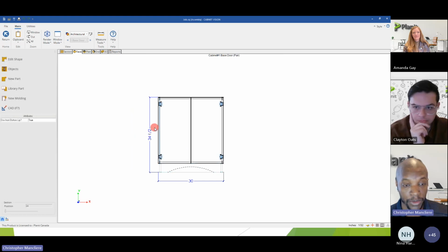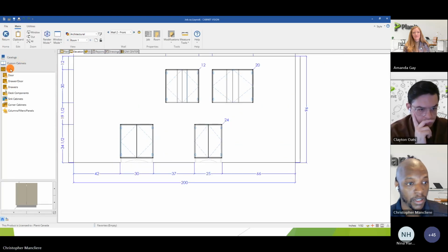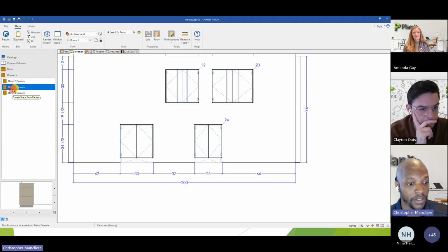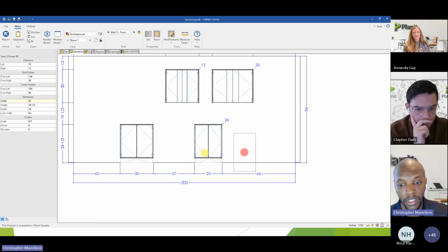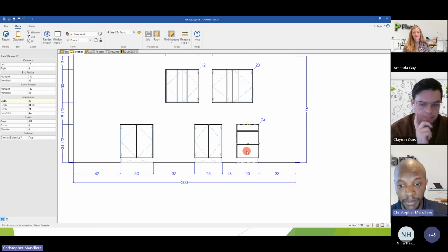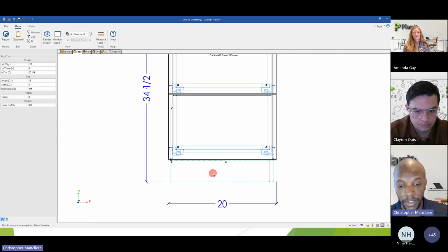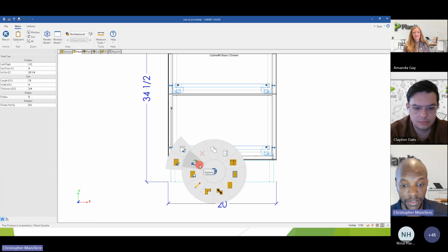And now how do you use it moving forward? So what you do is, let's go in the base cabinet library. Let's take a completely different assembly, the base 3 drawer. So what I can do now is I can go in my assembly, select the existing front tool, and when I select it, I right click. I have now a tool to replace the part with a library part. So under replace, you have replace with a library part.